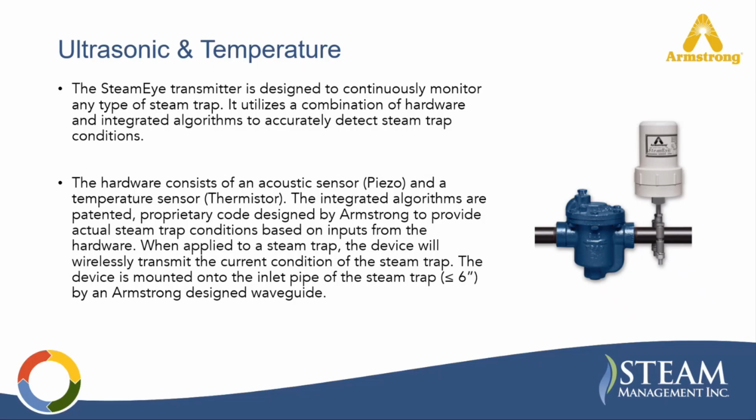Unlike the conductivity unit, which is primarily used on the Armstrong inverted bucket traps in level applications, the ultrasonic and temperature transmitter can be applied to virtually any type of steam trap. This includes inverted bucket traps, float thermostatic, thermodynamic traps, thermostatic traps, and many other trap designs.